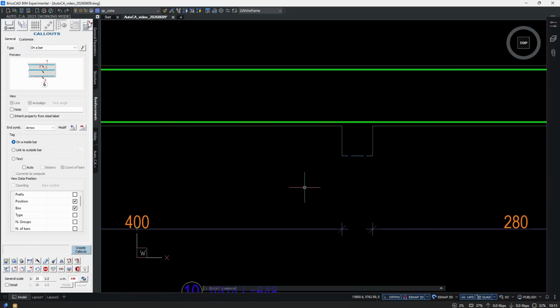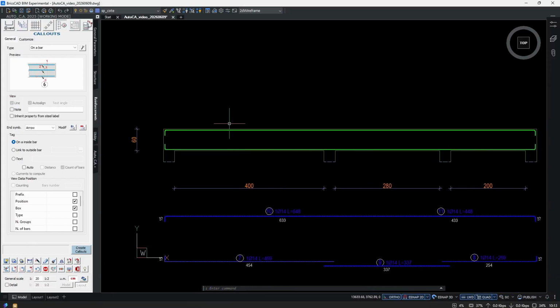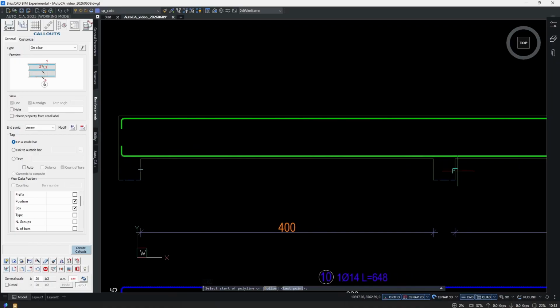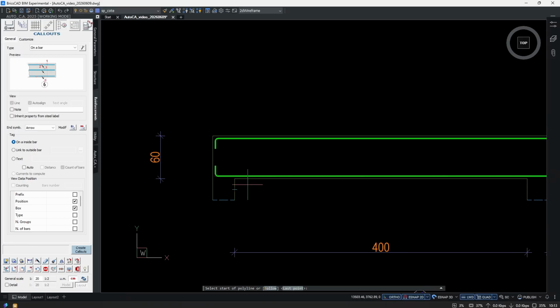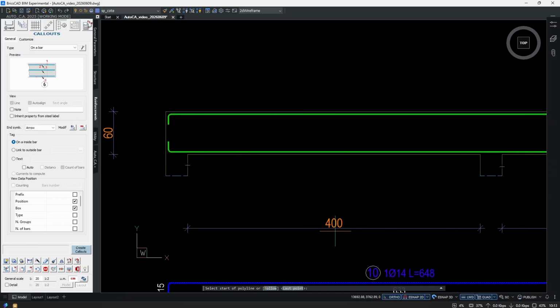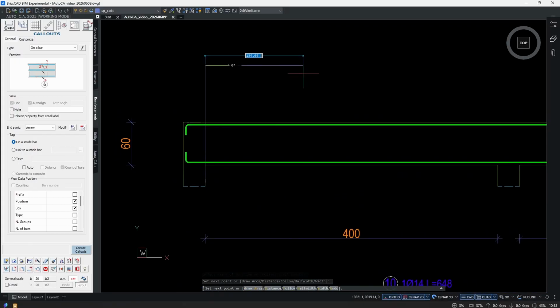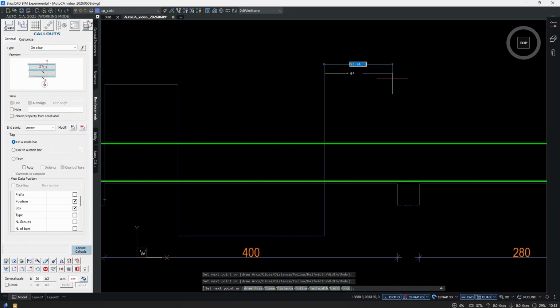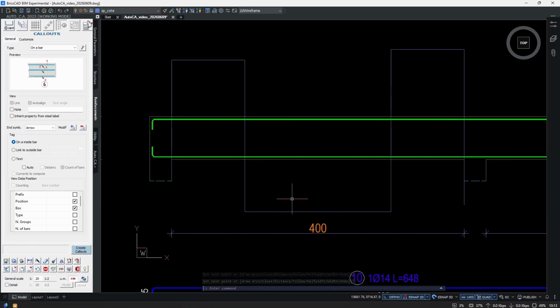To continue, we're going to create the 3-zone stirrup distributions. But before that, I'm going to define those 3 zones inside one single segment of the beam. So we have 400 centimeters, one segment. So we will need for one zone 100 centimeters. The middle zone is 200. And the last one is 110. That's it. These are our 3 zones.